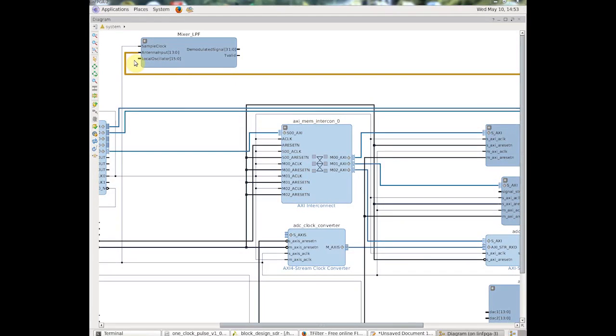But before we go ahead and do that, let's have a think about what we're doing here. So we're taking in a signal, demodulating it by beating it with the local oscillator. But if the local oscillator isn't exactly in phase and exactly the same frequency as the carrier frequency of the transmitter, we're going to see a bit of warble or variation on this signal here.